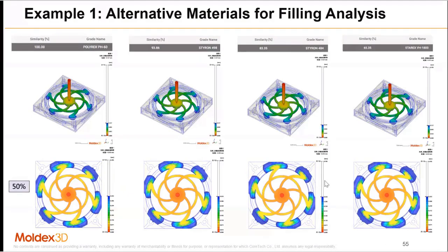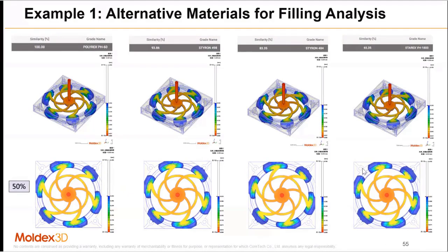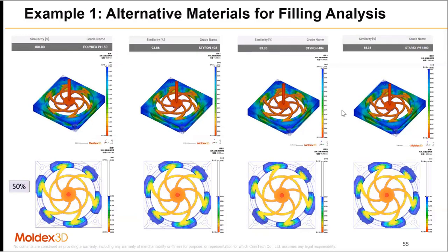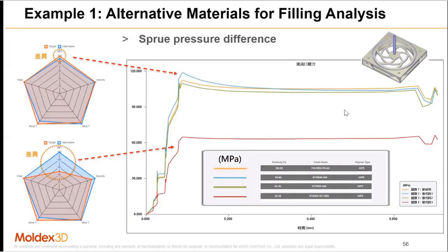So of course, for the feeding pattern you cannot see a big difference, because in this part the sequence is uniform, and you will see the difference in the curve, especially for the injection molding curve. For similar materials, their curves are similar. However, for a material where the MFI difference is big, you will see a poor prediction of pressure here.